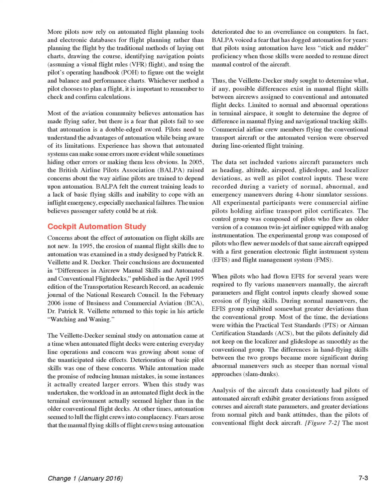More pilots now rely on automated flight planning tools and electronic databases for flight planning rather than planning the flight by the traditional methods of laying out charts, drawing the course, identifying navigation points, assuming a visual flight rules (VFR) flight, and using the pilot's operating handbook (POH) to figure out the weight and balance and performance charts. Whichever method a pilot chooses to plan a flight, it is important to remember to check and confirm calculations.